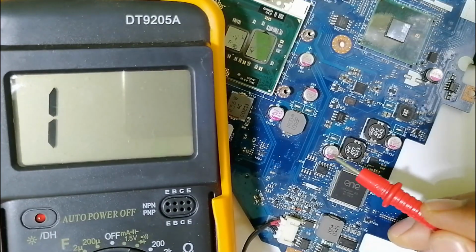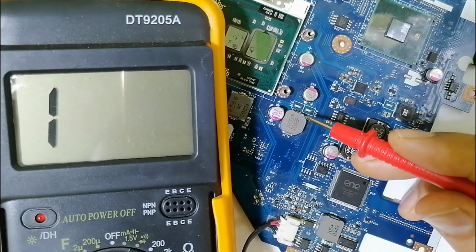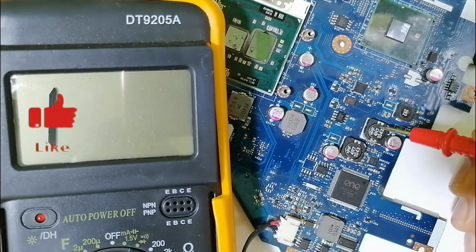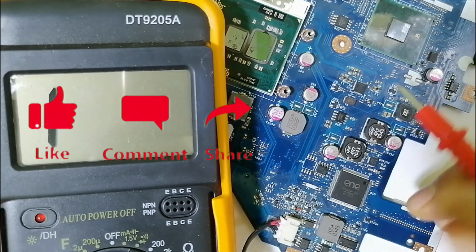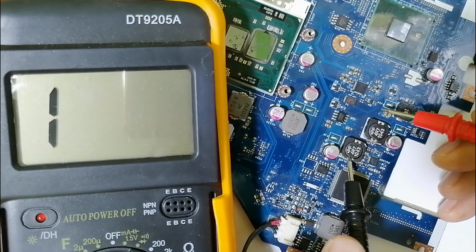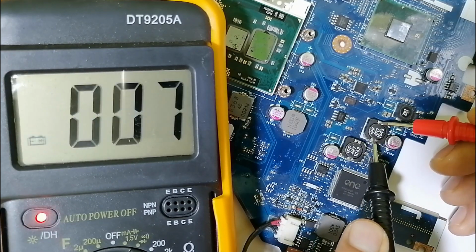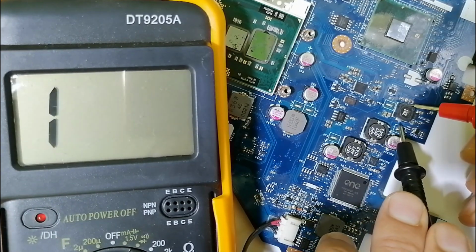We're gonna right now check these capacitors. Basically, these are electrolytic capacitors, but first, this kind of component is also like this and like this one. These are inductors. Always for inductors, you should find a continuity, as you can see here.